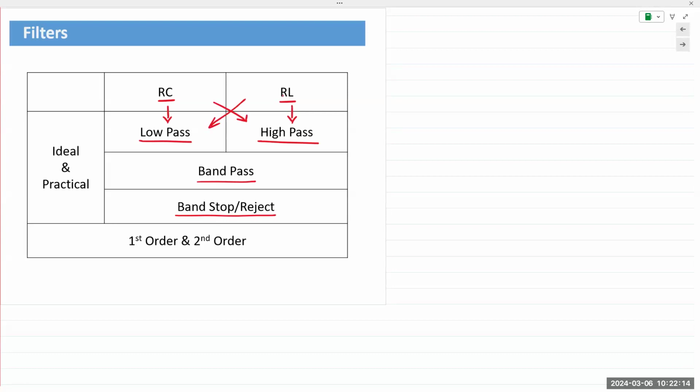Thinking back to chapter 4, if you recall, a one energy component device circuit requires a first order differential equation. It is known as a first order circuit, and hence a filter circuit built out of RC or RL, meaning only one energy storage component, is a first order filter.